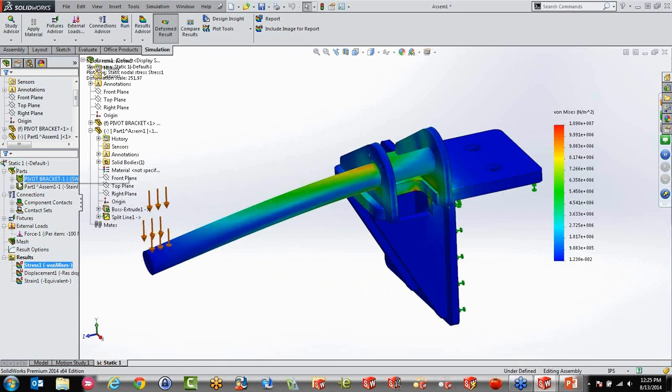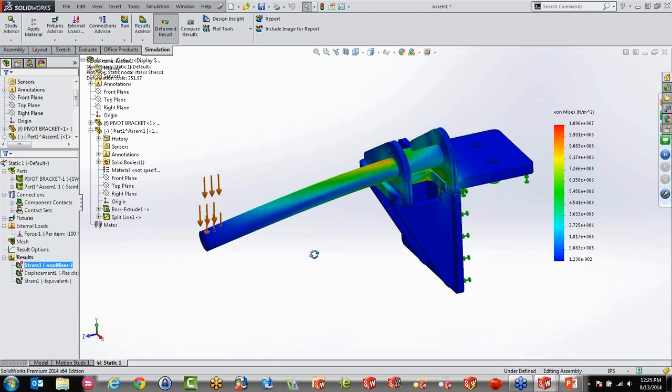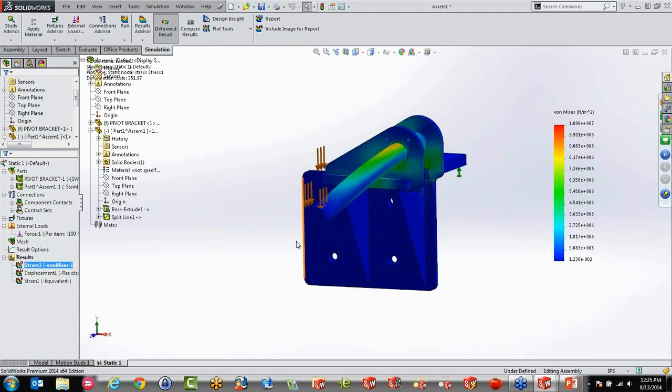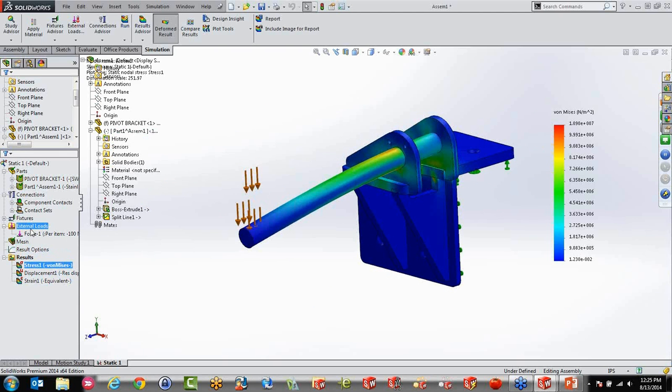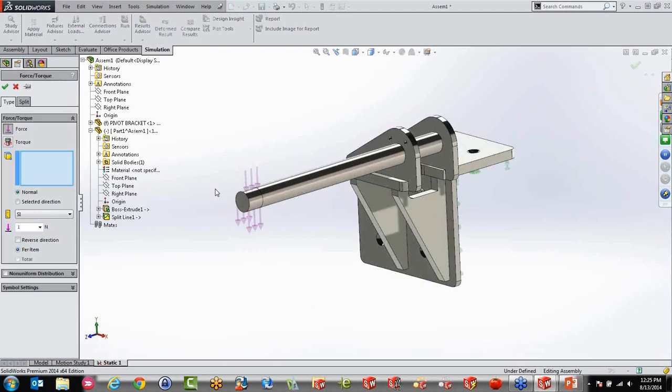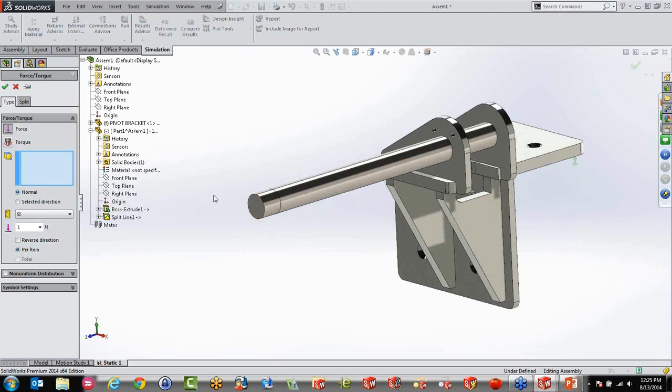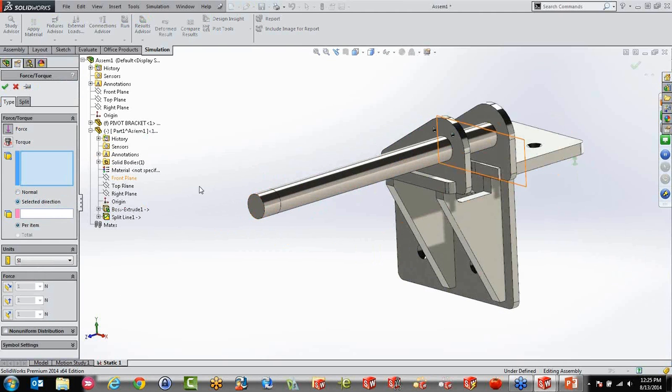We're working from the top, just working your way down, applying the different stresses. And you can, of course, apply more stresses. So if I know that this part is actually being pushed from other directions too, I can just add another force and say, all right, we're also going to have a force that goes from this face in another direction.